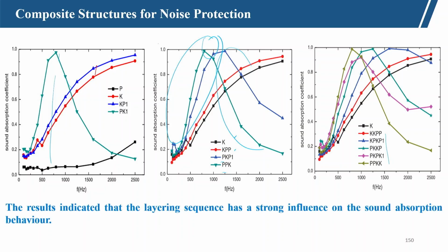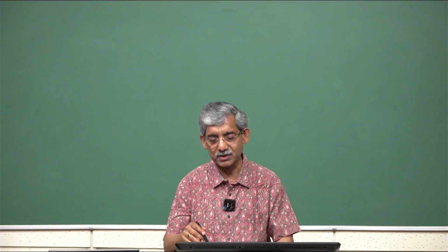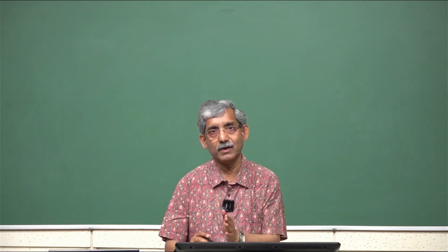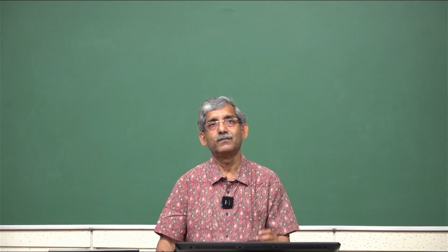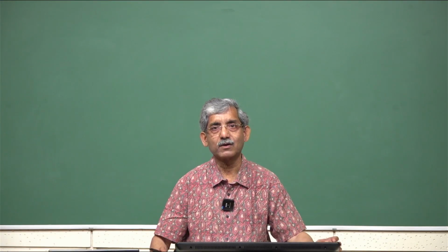Now, let us try to see the resultant. These results indicate that the layering sequence has a strong influence on the resultant sound absorption coefficient. A single layer has got certain sound absorption. If we have multiple layers, there will be some resultant sound absorption. So, if we have different combinations, different layering patterns, that will have a significant impact on sound absorption.